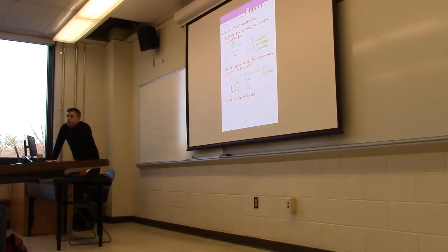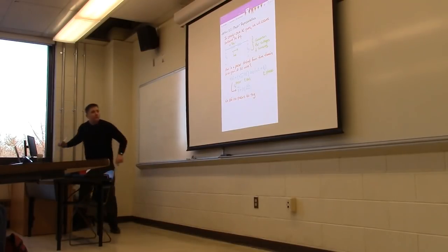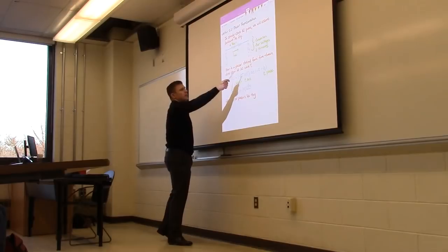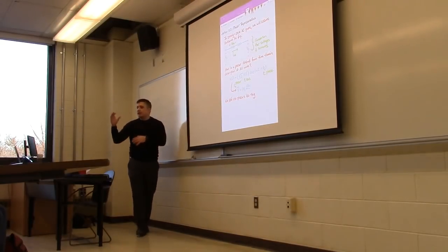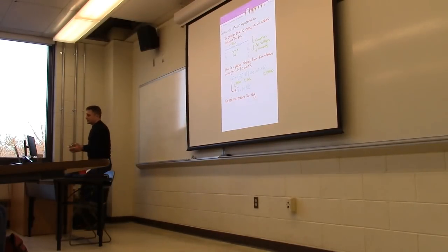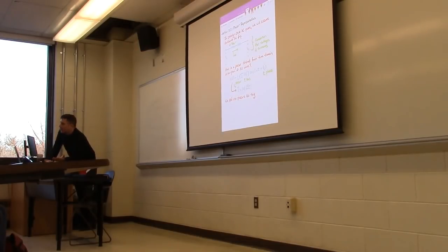If we try to do all these calculations with AC power and power factor and all that type of stuff, doing that with V of t times I of t and having to deal with all the time and the omegas, it just makes the calculations way more unnecessarily complex. So when we represent it in phasor form, like you said, it allows us to represent our impedances, voltages and currents in a certain form, and in the end it makes everything a lot easier.